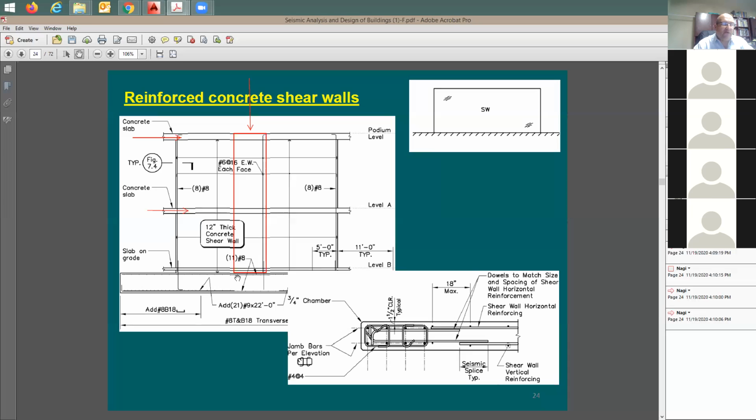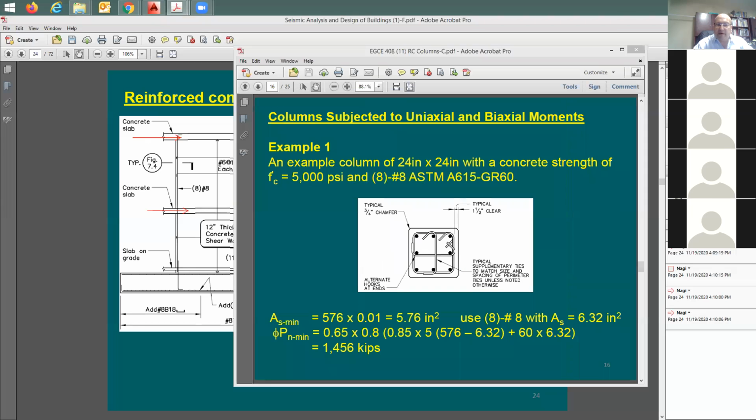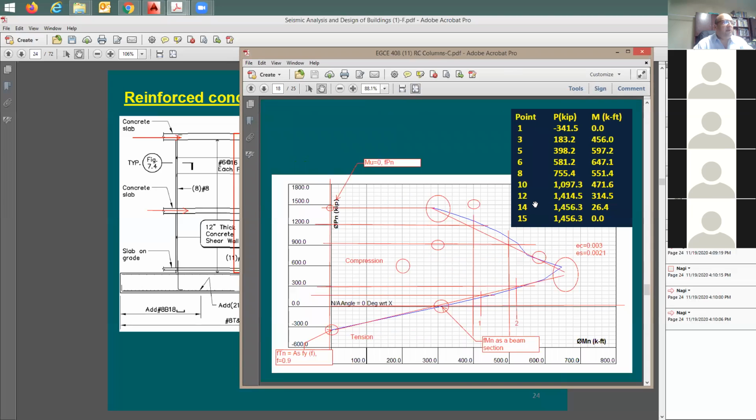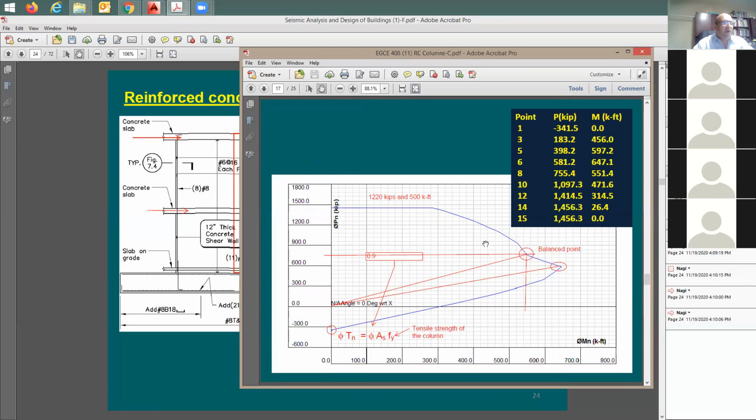Now you start to put the reinforcing, and for that, when you have this lateral force, which means moment and axial load, you're going to say, okay, now this reminds me of the interaction diagram. I guess I should be able to do an interaction diagram here, because what's the interaction diagram for? It's for a concrete member exposed to axial load, whether tension or compression, right?